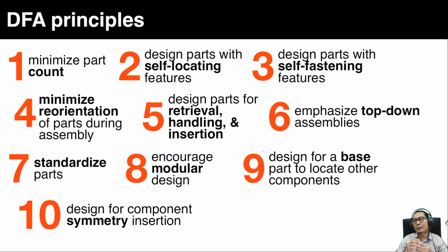The sixth principle is emphasize the top-down assemblies, so the movement is from top to down in the assembly process. And then the use of standardized parts. The following principles are encourage a modular design, and design for a base part to locate the other components. You have a base, or the main part, to locate the other components, and also design for components with symmetry insertion. So these are the 10 principles of the DFA.